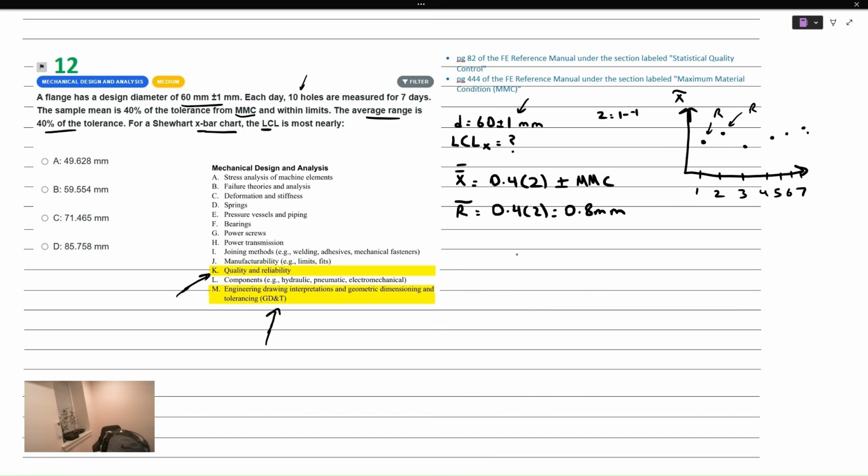So that's what the problem is asking, and it's focused on the lower control limit. So there's some bound down here called the lower control limit, and it's based on the average. And if we had a point below the lower control limit, we would say that something outside of random variation would cause a data point to fall below that value. And there's also an upper control limit, so something outside of randomness is causing a data point to fall above that specific limit, right? This would be the upper control limit. So we're trying to determine those limits in this problem.